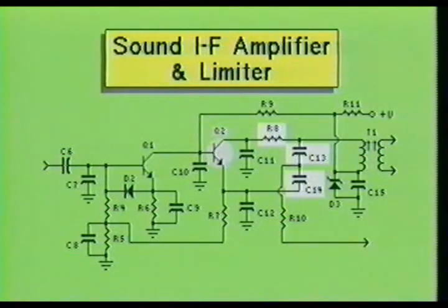Notice the loop circuit, consisting of transistor Q2's collector, resistor R8, capacitors C13 and C14, and transistor Q2's emitter. When transistor Q2 is biased off, capacitors C13 and C14 charge. When transistor Q2 is biased on, capacitors C13 and C14 discharge through Q2 and resistor R8. An in-phase signal reference for the next stage is provided by the junction of capacitors C13 and C14. The primary of transformer T1 is used as the output of the circuit and is the means of coupling the output to the next stage in the television sound strip.